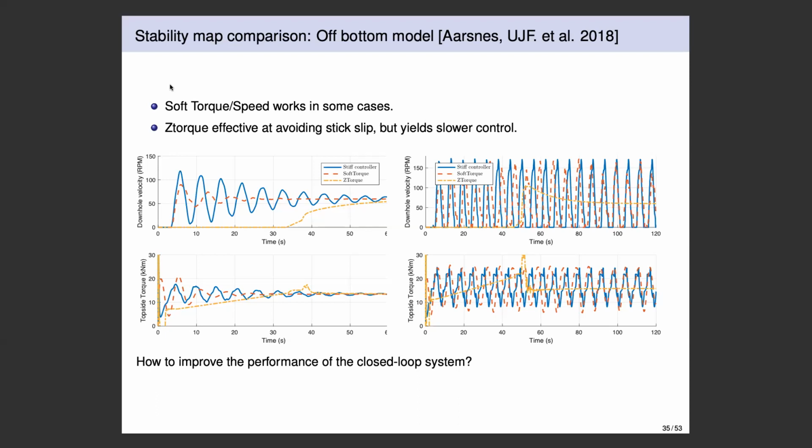The other, now that was the easy question, by the way. The harder question is, the guys that sell me Z-torque kinds of systems used to say, in the first implementation, I need a torque sensor below the top drive, and I need a speed sensor. Speed sensors are easy, we can get those easily enough. Torque sensors below the top drive have been more difficult and harder to come by and do well. So the current implementations of Z-torque that I've seen include a speed sensor that's, in theory, high enough resolution to get accelerations, and then use the top drive input torque as the other. Did you simulate that? In other words, I know I'm already getting an approximation for the torque at the top of the drill string when I do that. Did you simulate that, or what did you use for your boundaries up there?